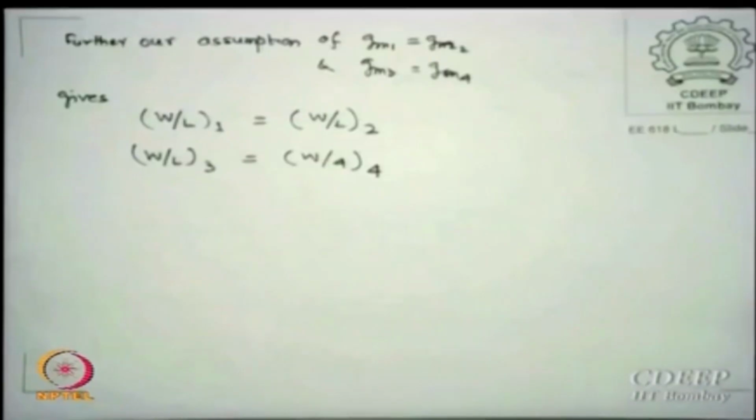If they are different, we can calculate with all different rO, different gM, so what? I mean, there is nothing very seriously problematic in getting all different, but in the normal case a differential amplifier design on an integrated circuit will give you this gM1 very much the same as gM2 and gM3 very much the same as gM4.